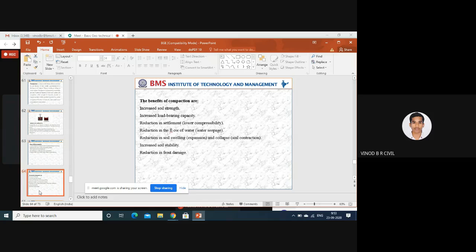it is undisturbed, and we can expect voids also. When you construct the ground floor and first floor, you can't expect any reaction. When you go to the second, third, fourth, fifth floors, then you can expect settlement. Whether it is unequal settlement or complete settlement, it differs, but we can expect settlement. When you go for compacted soil, you can't expect any settlement over there.